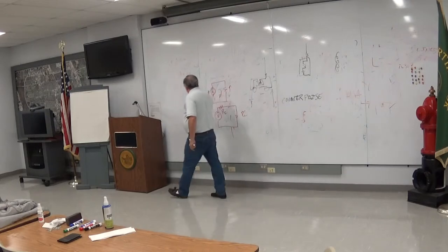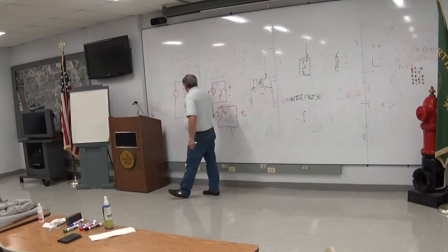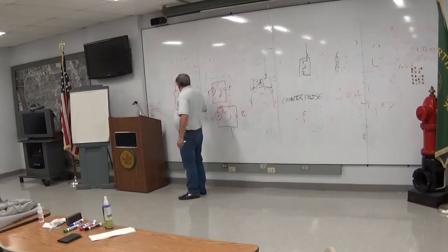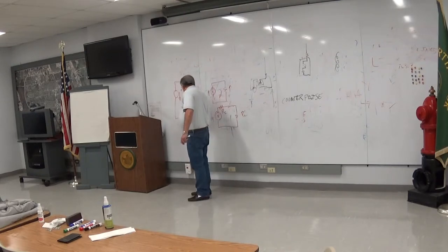If you happen to have some internal impedance here, you've got the element of a voltage divider. One of these things where you have two resistors in series. One belongs to the generator, one belongs to the load. The internal one and the external one. If this one is much higher than this, the voltage will drop across here and not so much here. And this bringing up of this resistance will reduce the overall current because Ohm's law still applies. Whatever voltage drop you get is going to be the current through the device times the resistance.